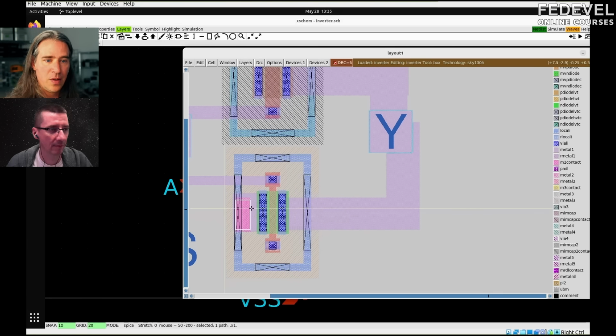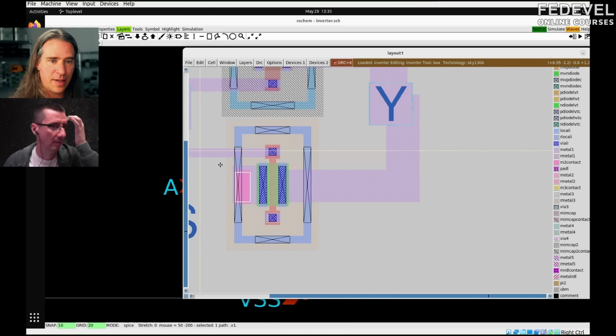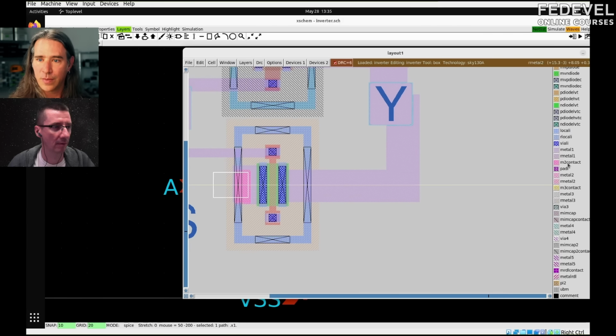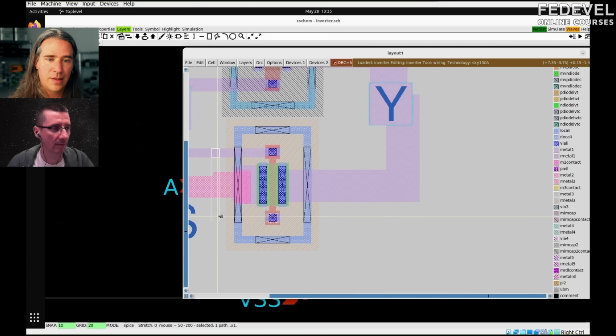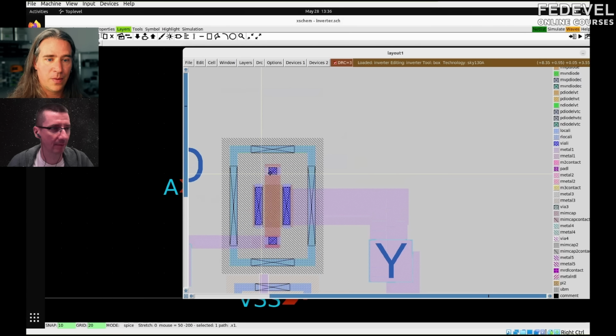Okay, finally. So I'll be able to get out of there with metal 2 and go to some ground. So metal 2, pop. Just pipe this out. And now here I want to come down. The crosshairs are really useful for knowing, okay, I should turn here. Whoop. And we got rid of that DRC. And we're going to have to do the same thing up top.